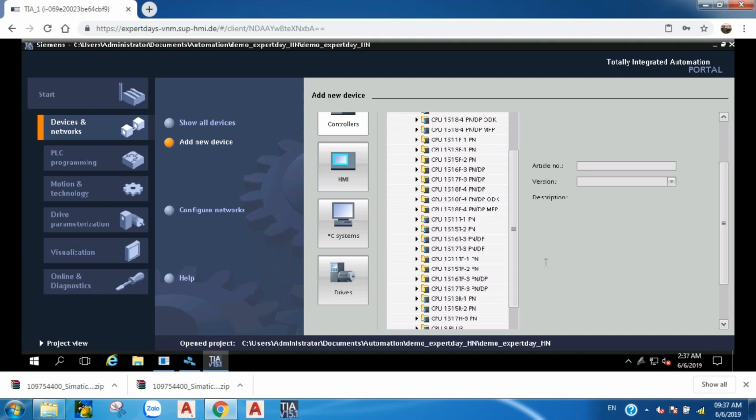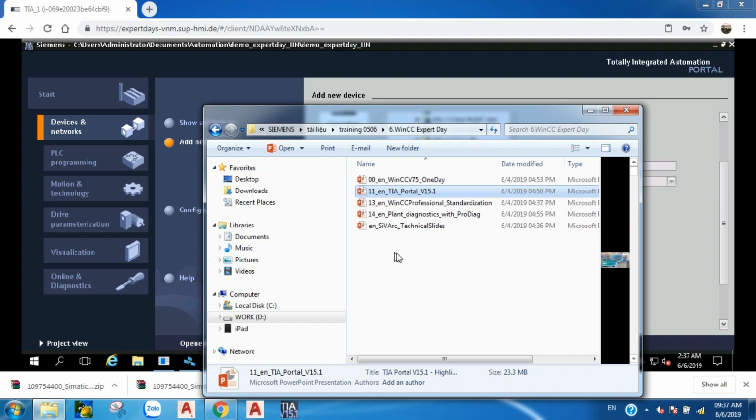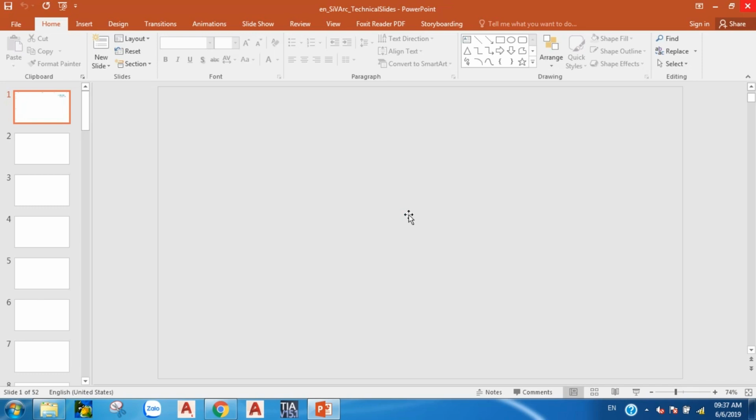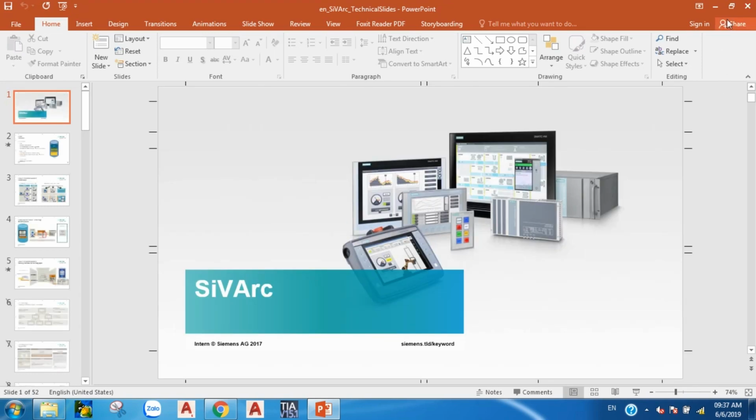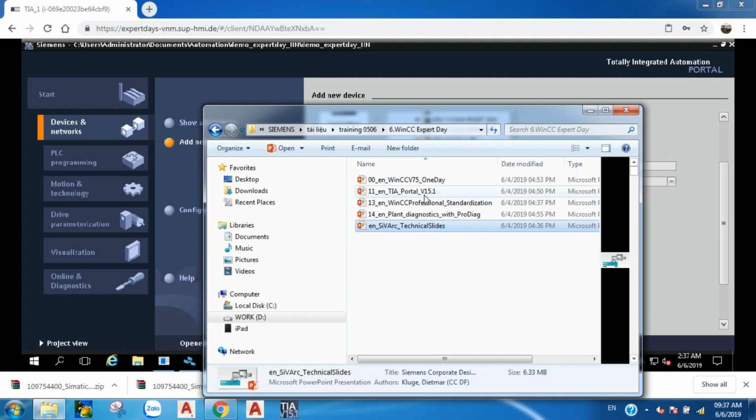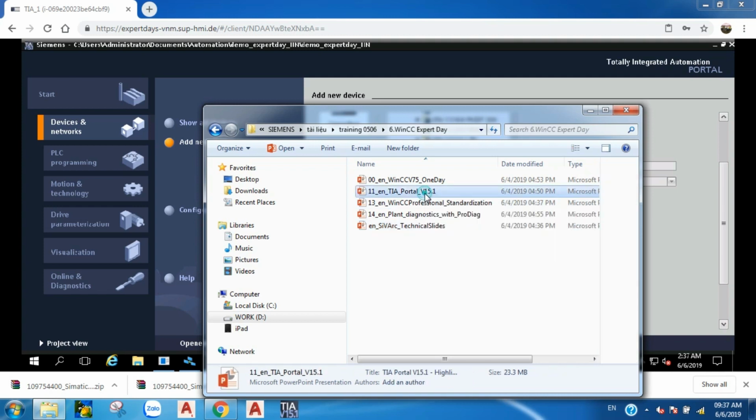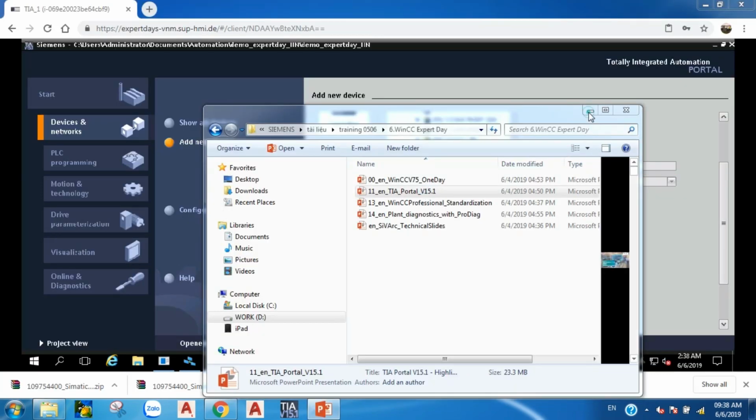CFC. We are also talking about CFC today. The one thing I want to mention is that yes, we do have access protection for CFC now over UMAC, which is the new user administration tool. We can also use CFC rules over Openness now, and support for STEP 7 STL blocks as well, and you can also set the XY position over the CFC expressions now.